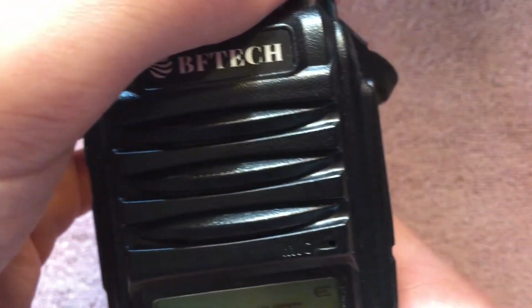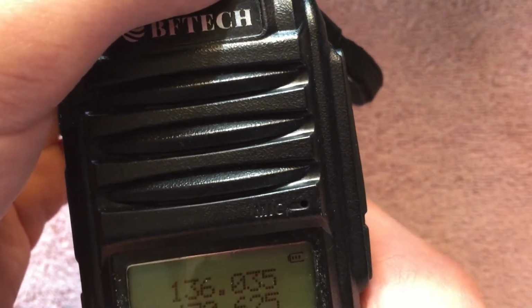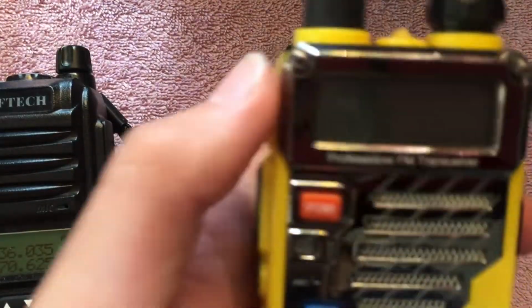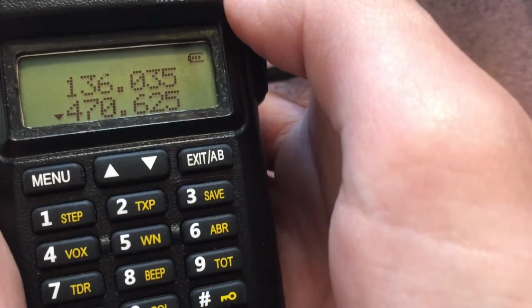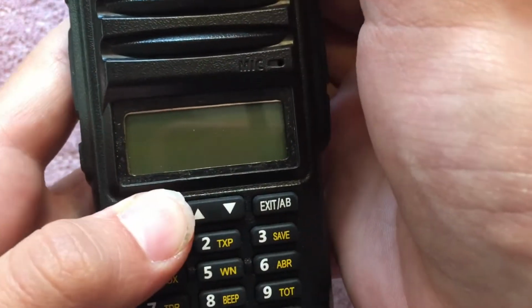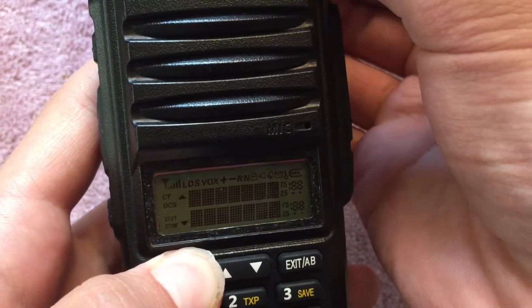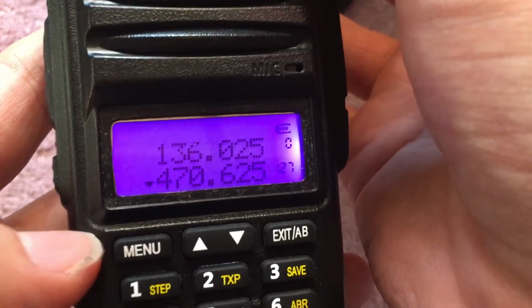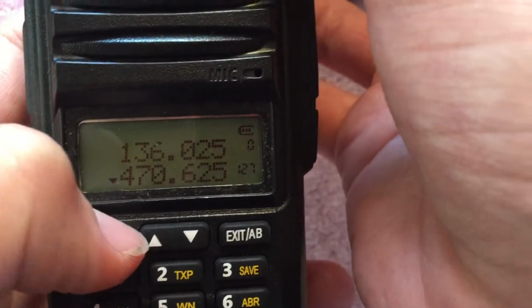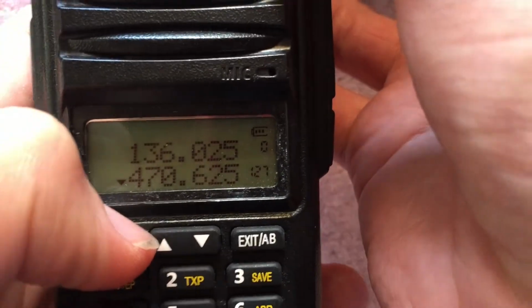first you're going to need to make sure you're in frequency mode, and there's two different modes, frequency mode and channel mode. Now on a regular Baofeng, this can be accessed by pressing this button and it'll switch between them. Now you may have some of these compatibles that don't actually have the VFO/MR button, and so what you need to do to switch between them is turn off the device, hold down the menu button, and then turn it on again. Channel mode. And in doing that, it'll switch between channel and frequency. I don't know why they're so lazy as to not include the button, but if you have one of these devices, that's how you do it.